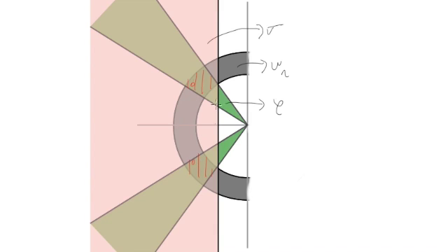So all the values that we find here, if we choose a system to have this pole and this pole, or this pole and this pole, they will be two different systems, but they will both satisfy the design requirement that the peak time is less than 2 seconds and the overshoot is less than 10%. So they will basically give us two different K values.